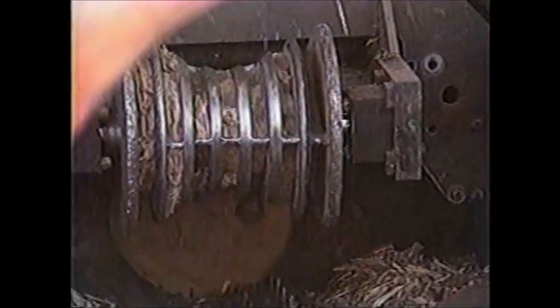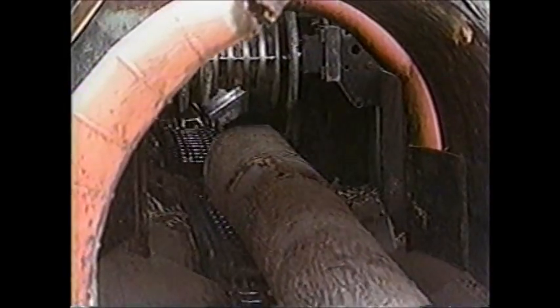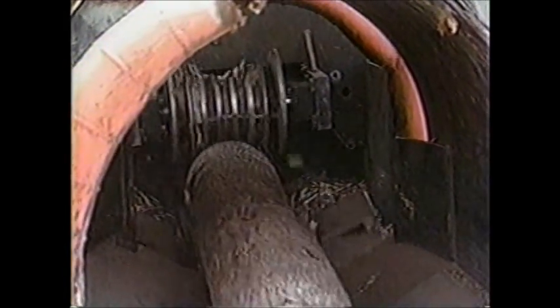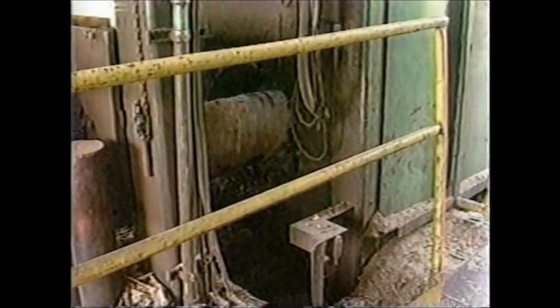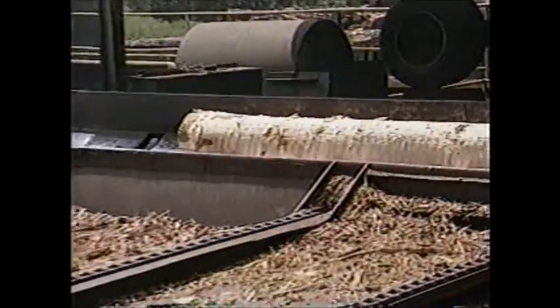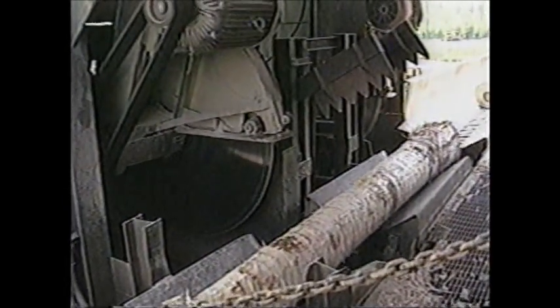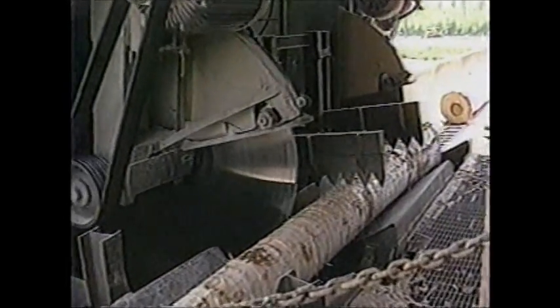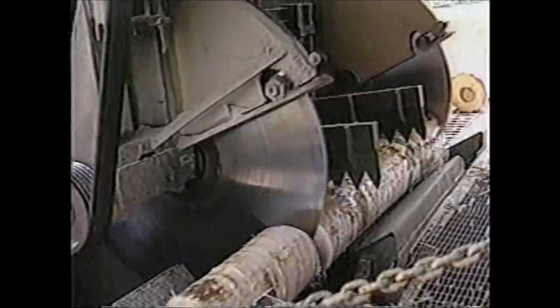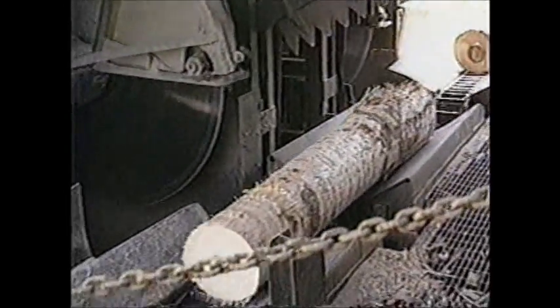The first step in the process is debarking. Here, a ring-type debarker, using rotating cutters, quickly removes the log's bark with its embedded dirt. This style of debarker is very quick and efficient. The biggest drawback is the diameter size limit it places on logs passing through it. After debarking, the logs pass through a deck saw where ends are trimmed and the logs are cut to 104-inch lengths. The trim from the saws, as well as the bark, is used as fuel in a waste-fired steam boiler.